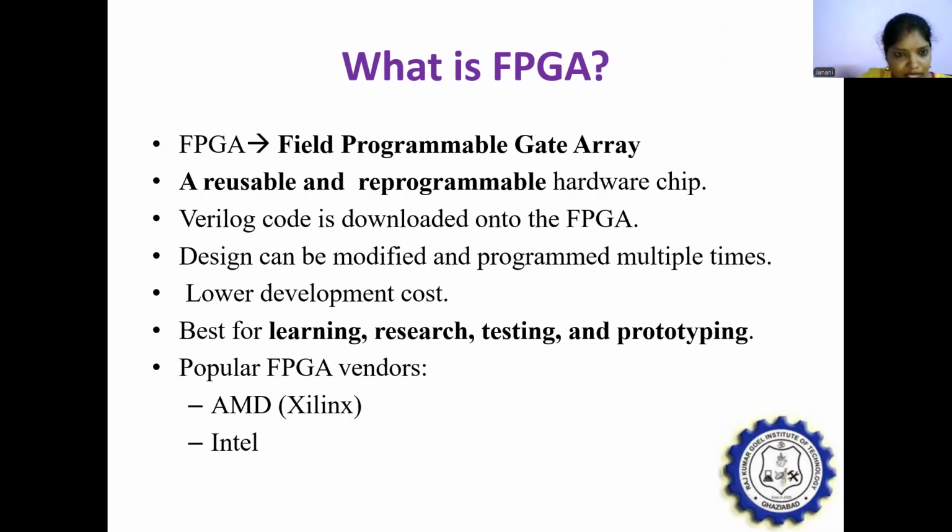The main advantage here is that if you find any error in the code, or if you want to update the features, you modify the Verilog code again, generate the bitstream again, and upload it into the FPGA board. So you can program the FPGA board multiple times; you can erase and reprogram it multiple times.